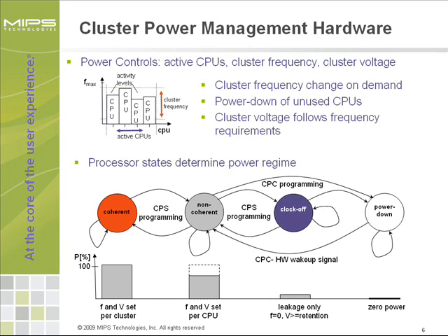Implementers might not choose the silicon area overhead associated with state retention solutions, or don't want to expand silicon area in power intent verification effort to implement power gating. In such case, clock off mode and voltage reduction for this CPU can provide viable alternatives. However, the implementation choice comes with an increase of wake-up latency since external voltage regulator programming times and slew rates must be awaited before clock can be reapplied.